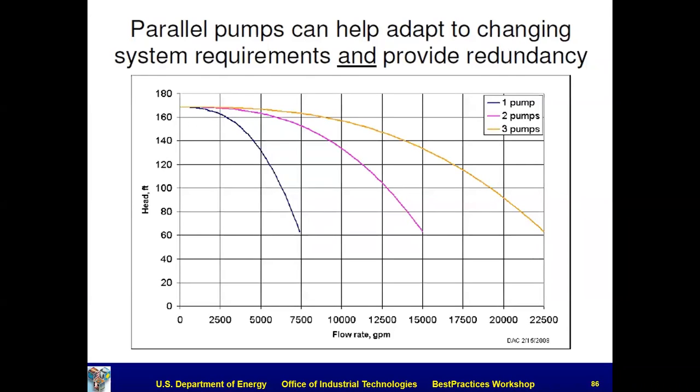And so if I'm going to run two pumps in parallel, what I do is I pick a bunch of these different heads. For example, I pick 140, and whatever the flow is here, I multiply it by 2. And so that puts me out, and this becomes a point on the 2 pumps in parallel curve. If I run 3 in parallel, guess what?